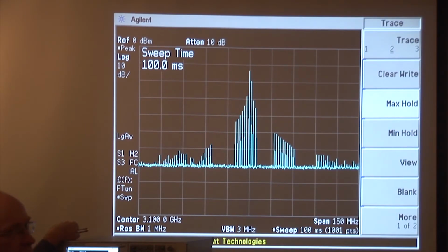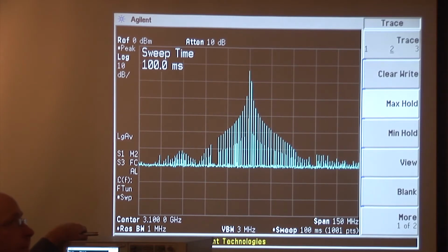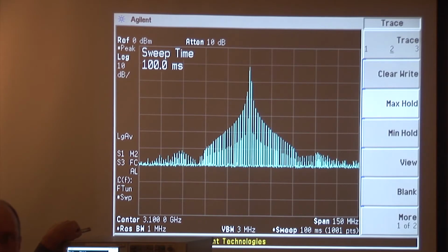And remember, this radar is rotating, like I said, once every second, so you won't really get this kind of a gift if you're measuring one out in the real world. Although some maritime surface search radars might have a 2-second rotation, and there are some airborne radars that might sector scan back and forth every second. What about the radars at airports, you know, that look for ground traffic? Oh, the ground surveillance radars, Bob asked, what about the ground surveillance radars at airports? Those do have a 1-second update rate. So yeah, those are 60 RPM, so they would rotate around as fast.